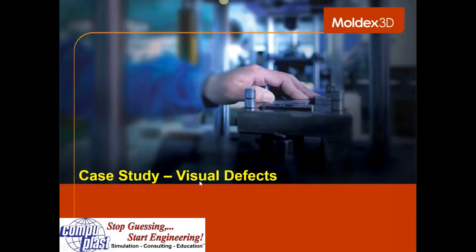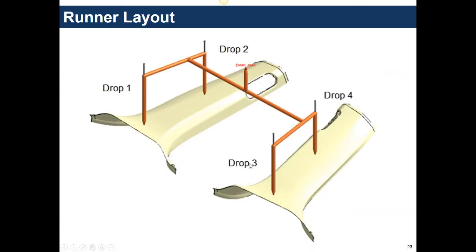The next case study has to do with visual defects. Now, this is a case of an automotive part. You see this is a 2-cavity mold that is fed by 4 drops. Now, sequential molding has been around for a long time. To avoid weld lines, people will time the opening of these drops to control the flow fronts to avoid weld lines and get the filling pattern that they require. Simulating this has also been around for a while. We've been able to simulate sequential molding.